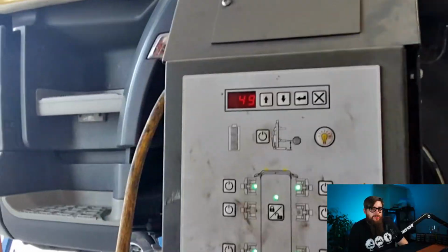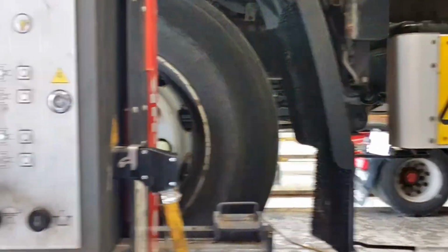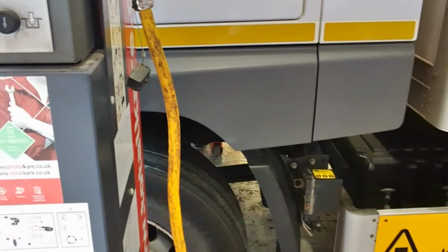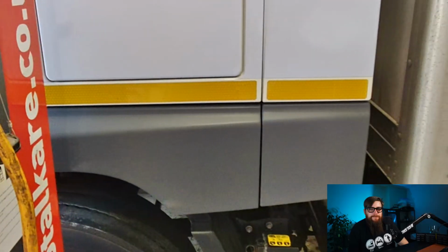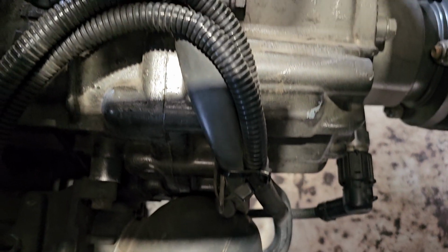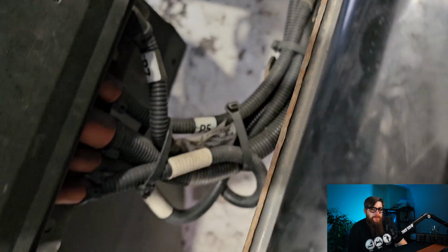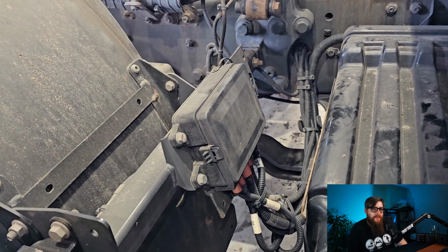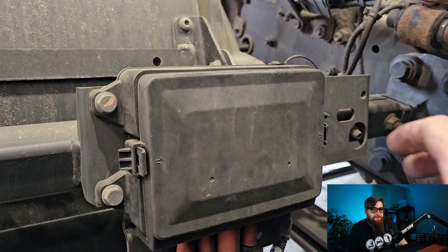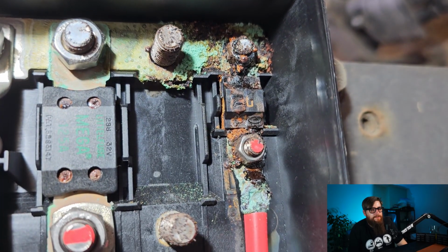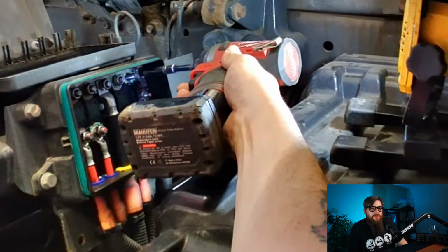I'm going to have to trace this loom to its source, so down comes the truck. With the truck down on the ground, I can get the cab over and follow this harness up the back of the gearbox to the PDU, or Power Distribution Board, located on the wing for the LF. What will our watertight cover reveal today? Our old friend corrosion, or in this case, high resistance. It's a bit of a stretch to get this fuse out.